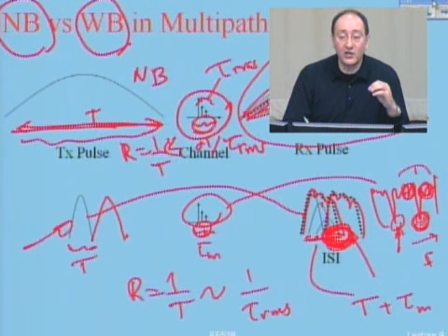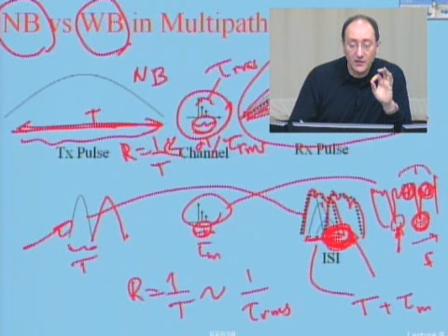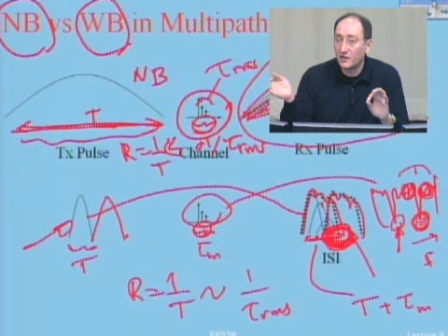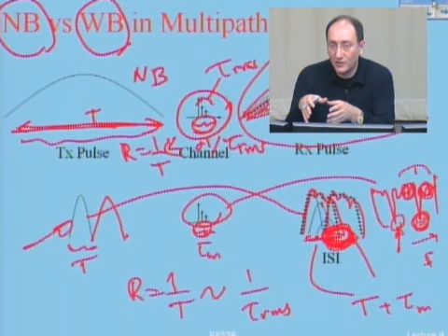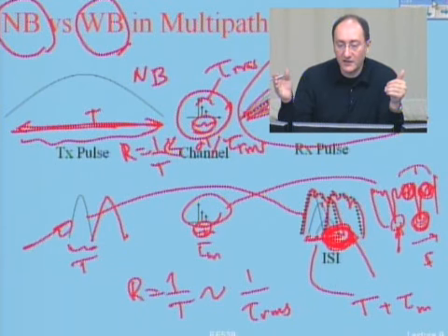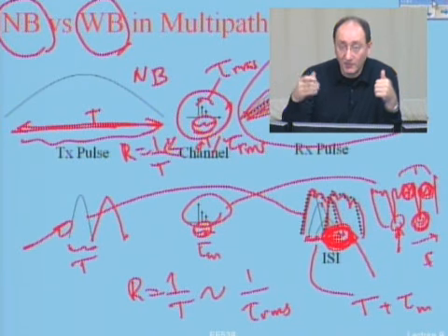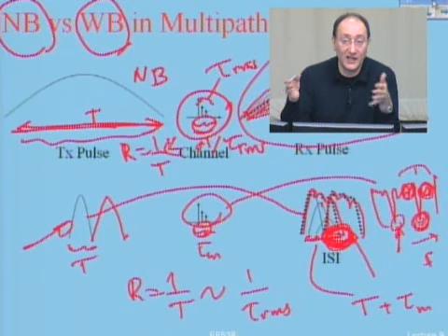So, in narrowband communication, in the frequency domain, I'm disturbed by frequency selective fading. As time passes by, either the entire signal goes to fade or the entire signal is out of fade. If I increase my data rate, my bandwidth becomes wider, so the probability of having a fade inside the bandwidth increases. And I'm in deep trouble.